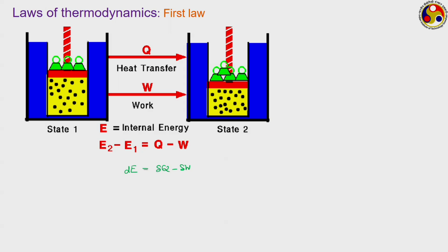If we want to analyze a system, then we have to do this for the entire system and sum all of them up. Think about a particular cycle; let us plot that on a property diagram, say a PV diagram. So, we pick up some standard processes. Let us say our process initially starts with a compression process from point 1 to point 2, which is at a much higher pressure and low volume. Then we have a constant pressure, that is isobaric, expansion process, during which pressure remains constant but volume increases to 3, and then we have another process during which the system comes back from 3 to 1.